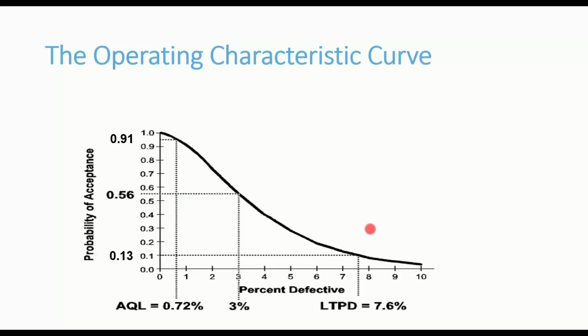And then I have a note here that you should document the AQLs and LTPDs of all of your sampling plans, of course, also your alphas and betas, right? The AQLs and the LTPDs of the military standard that we'll look at, and the ANSI Z1.4 sampling plans, can be determined using tables. There are 3 tables that you kind of have to look through. One table tells you information to put in the next table, and it tells you information to put in the third table. You don't really need those for that, but you do need some probabilities of acceptance and such.